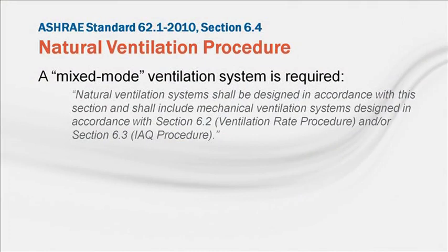One key part of this new natural ventilation procedure is that it requires mixed mode or a hybrid approach for most applications. Here's an excerpt from that standard. It states that when natural ventilation is used, the building shall also include a mechanical system to ensure proper ventilation whenever the natural ventilation openings are closed.